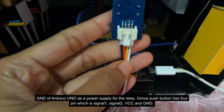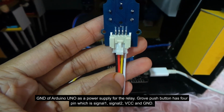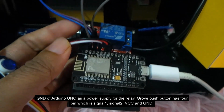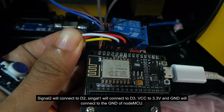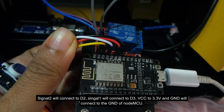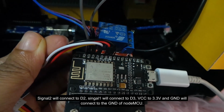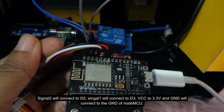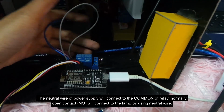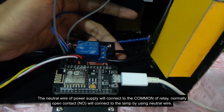Group push button has 4 pins, which is signal 1, signal 2, VCC and ground. Signal 2 will connect to the D2, signal 1 will connect to D3, VCC to 3.3 volt and ground to ground of NodeMCU. For the wiring, the neutral wire of power supply will connect to the common of relay.